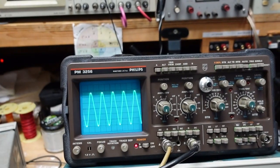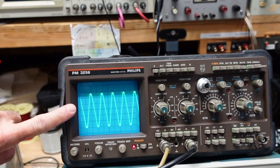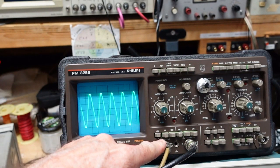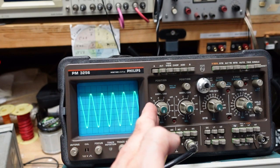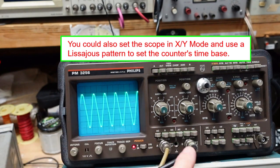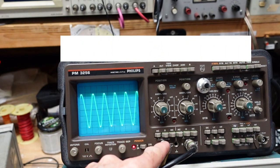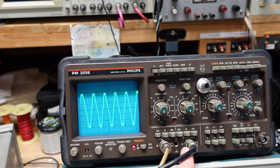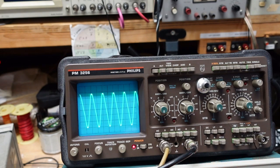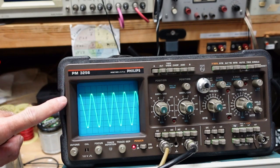But that's what you do. You would put your reference in, trigger from your reference, and then set channel 1 until you get a stable presentation, not moving to either side. And that's why you would trigger off of one channel while observing another. Channel B, or channel 2 here, is our trigger. Channel 1 is depending on the trigger from channel 2 to get a stable presentation.